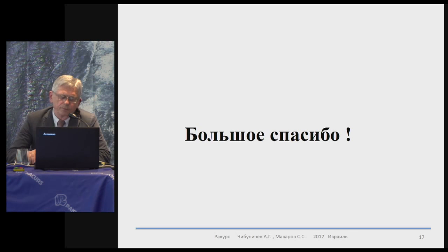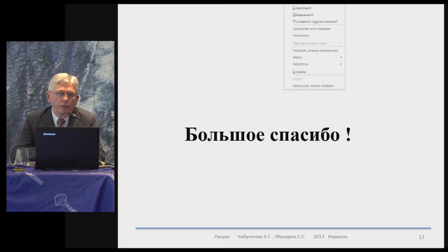correctly. In terms of geometry of coordinates, you said that you arrived at 21 images. That could be, but I would say there could be fewer images necessary. But for complete information, 21 is better than 10, for sure. But if your processing algorithm takes into account geometry of each point, including the resection point, I guess 10 should be enough.